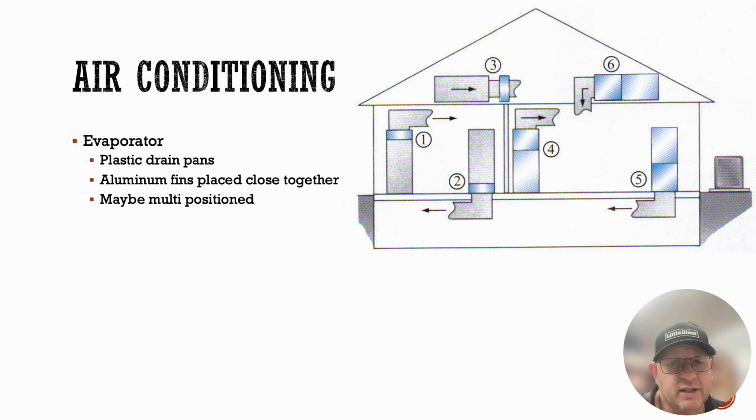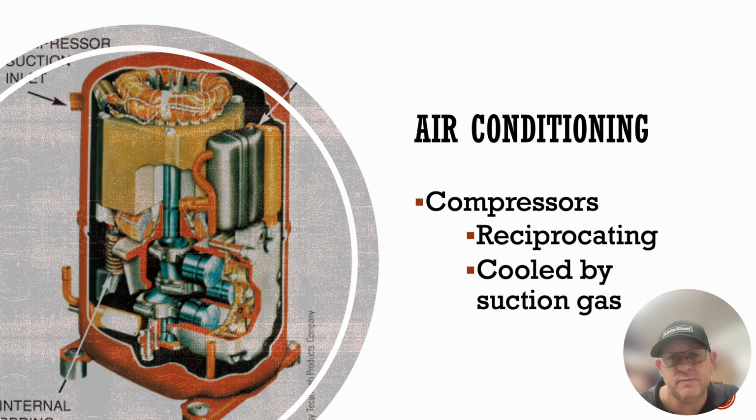We can see that we can still multi-position the evaporator on the furnace to be upflow, downflow, or horizontal left or horizontal right application. It doesn't matter a lot about these systems and the positions that we can put them, because we have many ways that the manufacturer has given to us to actually position the evaporators, run the drains so that we can effectively cool that environment down inside the house.